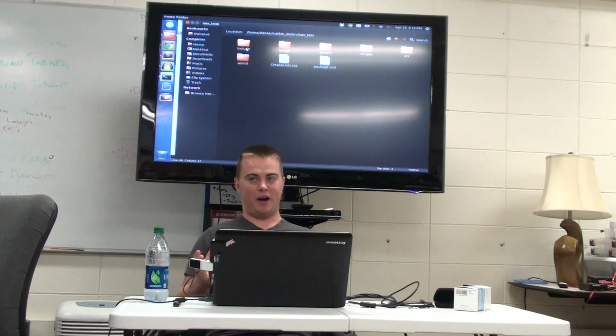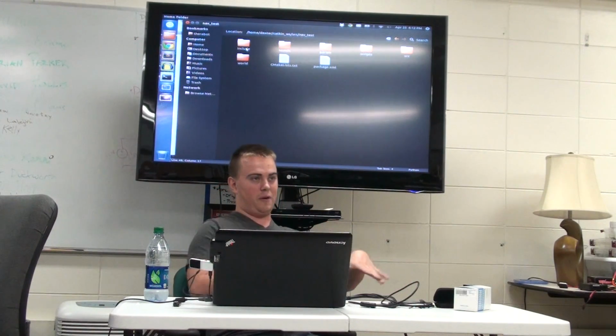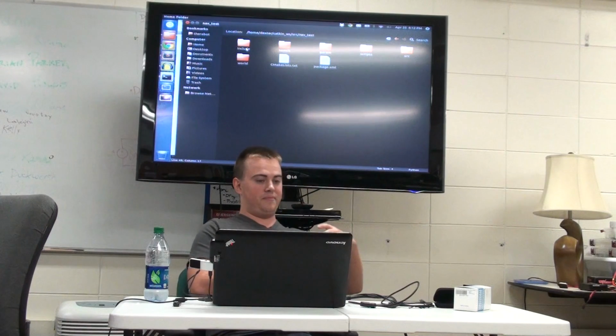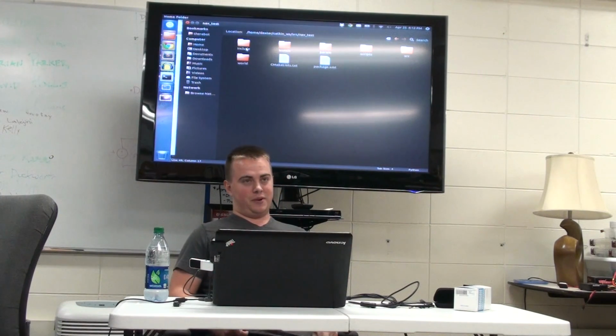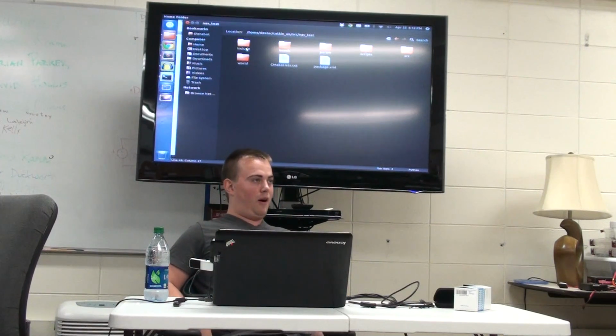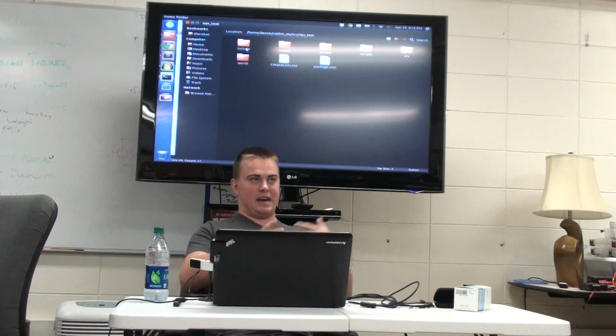because the way that ROS works is it's essentially an interpreter between your hardware and your actual programs. If you have a robot, for example the Jaguar off in the corner there, it has a bunch of onboard embedded hardware, and that does stuff. It translates from velocity to motor driving. It translates sensors to actual output data, things of that nature, and then it takes that data and sends it over a serial, Ethernet, or some kind of connection to your actual computer. When it's on your computer, it's not in ROS. It's just in a serial port or Ethernet port or wherever it is. To get it into ROS, there is a bring up file which launches a bunch of nodes that then convert the data back and forth for you.